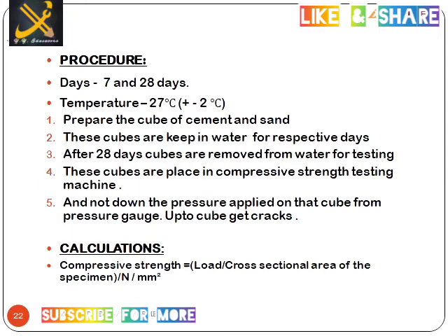Procedure of compressive strength testing. The test is conducted at 7 days and 28 days. Temperature requirement should be 27 degrees Celsius plus or minus 2 degrees Celsius as per the IS code. Prepare the cube of cement and sand. Only cement we should not test, so sand will be added to the cement and make a